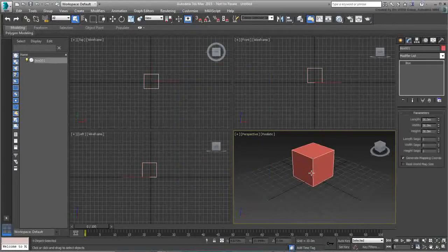The box, which was initially set to 3 feet in size, or a little less than 1 meter, is now 36 meters in each direction. You would then need to scale it down or edit its parameters to bring it down to the correct size. It's easy enough with one object, but more complicated if you had dozens or hundreds of objects in the scene. So, let us explore a bit more how to work with system units and how to set them up.